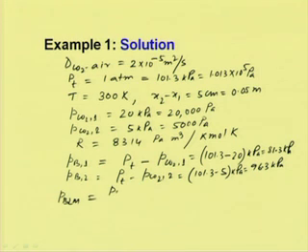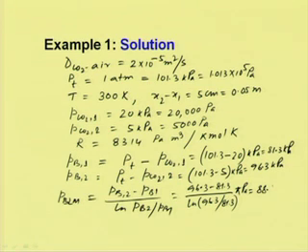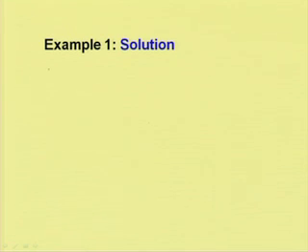which is PB2 minus PB1 by ln PB2 by PB1. So, putting the values, 96.3 minus 81.3 divided by ln 96.3 by 81.3 kilopascal is 88.59 kilopascal. So, which is equal to 88590 pascal. So, now if we substitute in the flux equation for NCO2, we can write this is diffusion coefficient 2